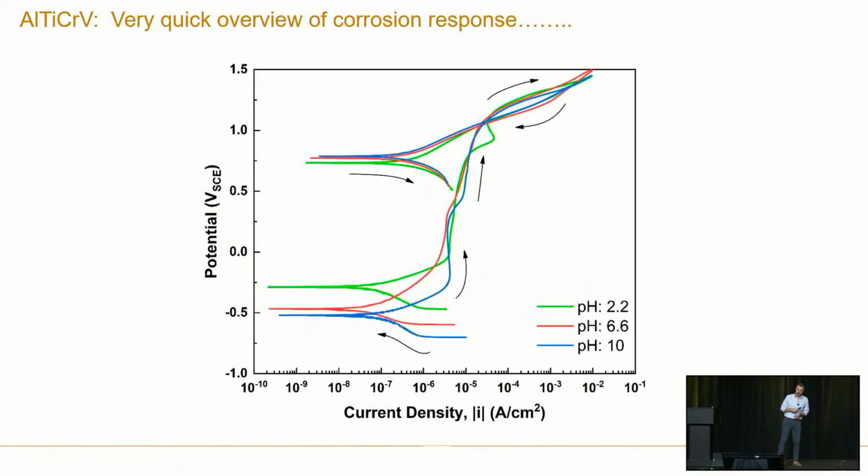All right, but I'll just put this up by itself because I think it merits its own slide. As far as I know, there's a lot of corrosion-resistant alloys out there. But we got really excited when we did the corrosion rate testing of this, where we saw across a range of pH a very huge window of passivity for this particular alloy, with also a very favorable hysteresis. So it repassivates quickly after it starts to dissolve.